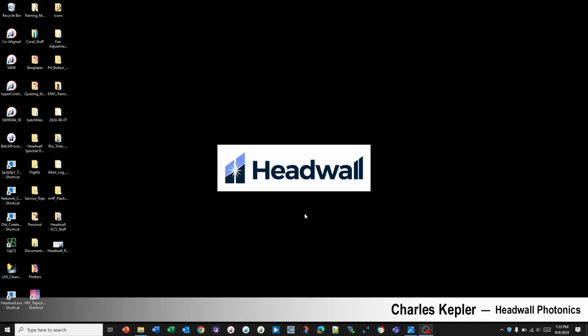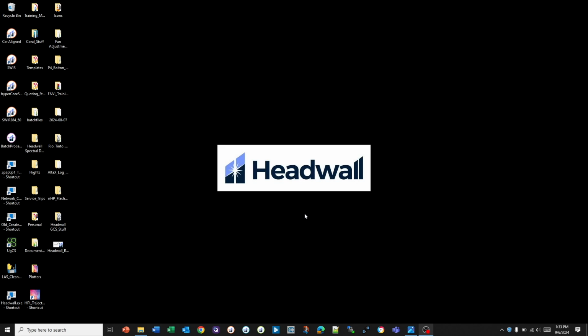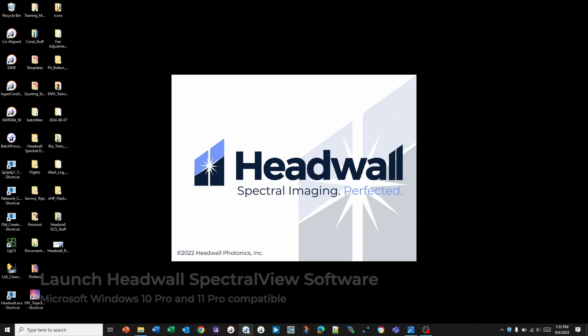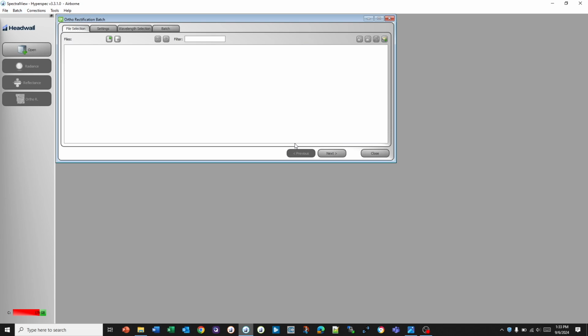I'm an applications engineer and lead pilot here at Headwall Photonics, and today we're going to walk you through the steps of doing your orthorectification. So the first thing we're going to do is launch our Spectral View software. In a previous video we went through the conversion to reflectance, generating our SBET and generating an elevation model to use. And so now for the orthorectification we're going to do a batch orthorectification.